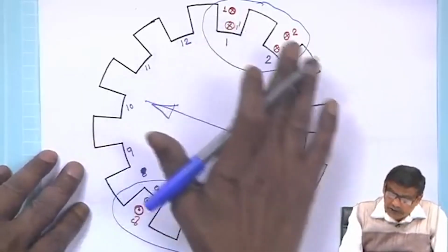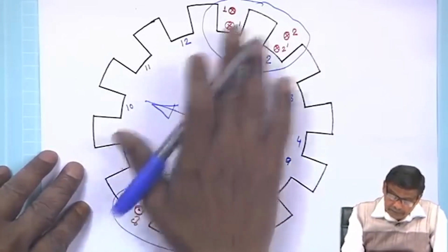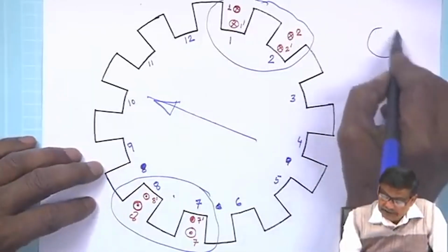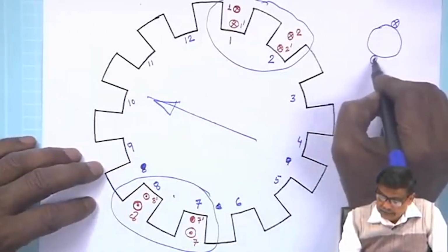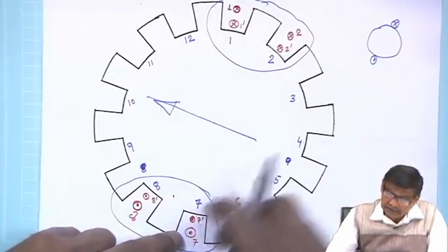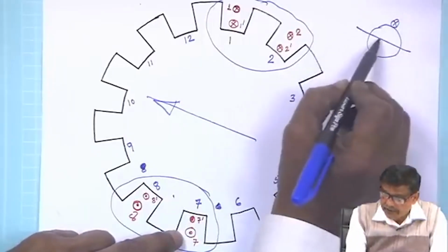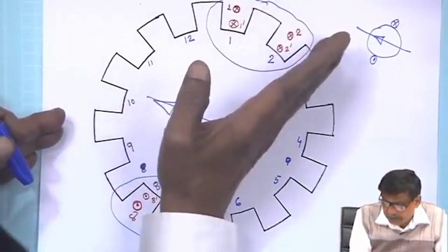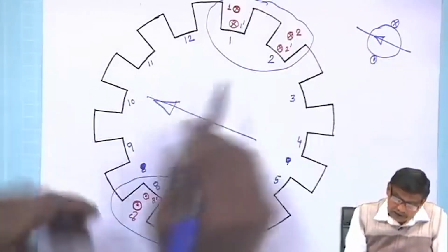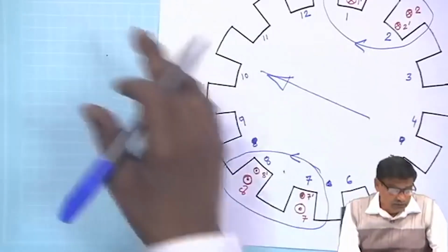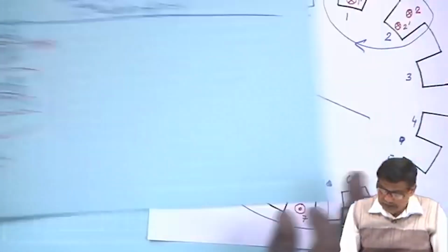Therefore, by distributing the coils, if it is a 2-pole machine, that is the distributed current pattern. If coils were not distributed, all were in 1 and 7 dashed, then it will be like this and your field will be like this, 2 poles. Similarly, if these currents are distributed now, they can be grouped together and you still get 2 poles, that is the thing. Achha. After this is over, we have understood the 1-to-1 correspondence of this to this.